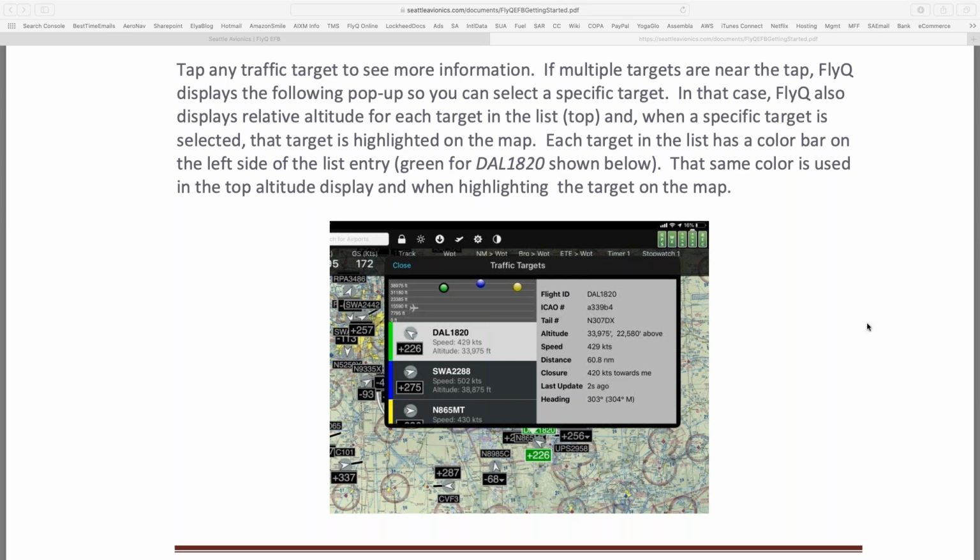Whether it's core functionality that you need in your ADSB receiver, it kind of doesn't necessarily have anything to do with ADSB. It's more just a matter of packaging in that your iPad or your iPhone can only connect to one Wi-Fi device at a time. So if you had multiple devices, like a standalone AHRS and a standalone GPS and a standalone ADSB receiver, your iPad couldn't talk to all 3 at once. It would only be able to talk to one. Consequently, the manufacturers just started building all the hardware devices into one box, and then that one box gets transmitted. Pretty clever, actually.